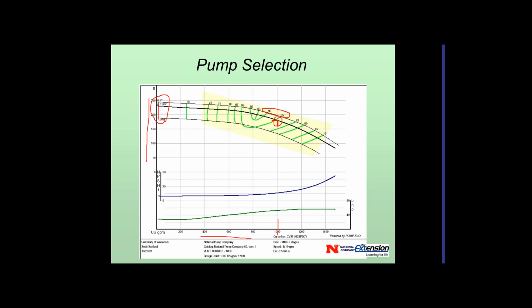The other thing we've got down here is net positive suction head required. Previously I said we have to have a certain amount of feet of head for the pump to work. So here's where it's going to be. I've got 0 and 25, so this is 12.5. So this is maybe 13 feet of head here to run that.